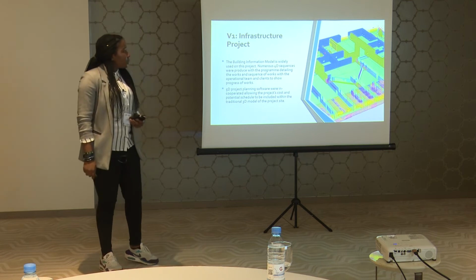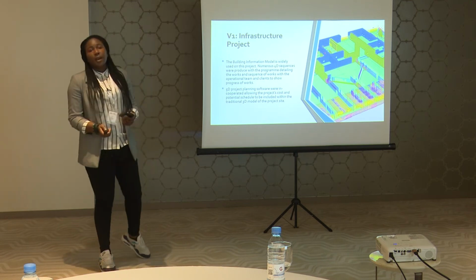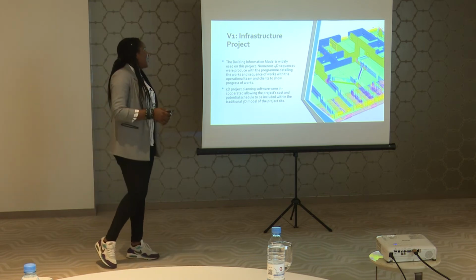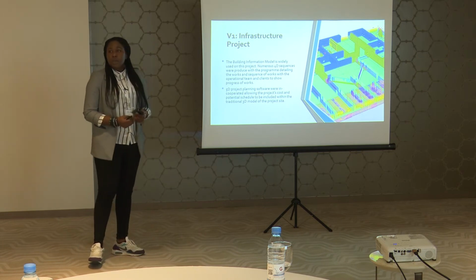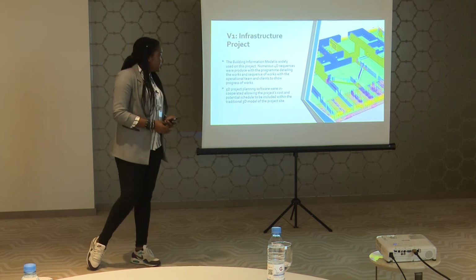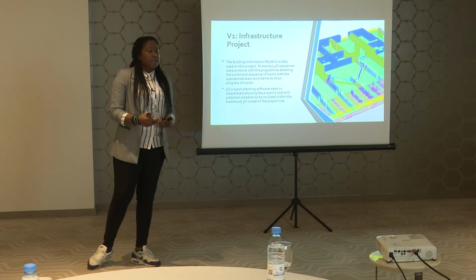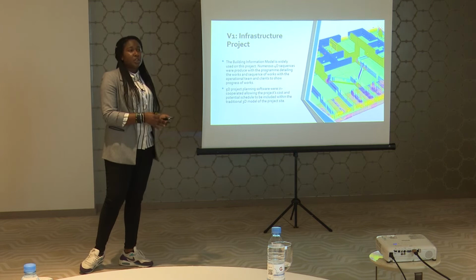So in terms of Industry 4.0 technologies, they implemented BIM. You would find that all the projects I'm going to talk about have BIM, obviously. They basically used the building information model from the designers to create 4D sequences. Because they had to excavate a lot of material, these 4D sequences were very helpful for the site team, so that they can know what material they're meant to excavate, what time and what stage they're meant to be at.